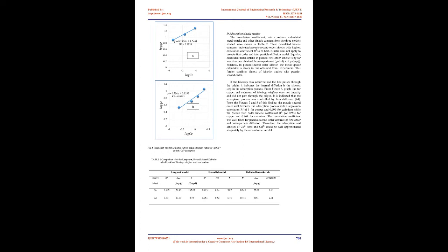2. Surface area and porosity. In this study, the surface area and porosity of the prepared activated carbon were analyzed. The BET surface areas were found to be relatively high. The smallest surface area was 396.9325 m²/g and the largest was 435.1738 m²/g when pyrolysis was done at 700 degrees Celsius. The total pore volumes measured as higher for single point and micropore were 0.189245 cm3/g and 0.153732 cm3/g respectively.